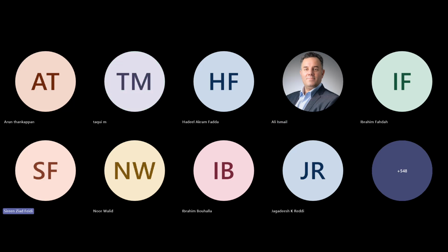They have to refer back to the circular. For specialized buildings, it is required to submit a BIM model. Although I doubt very seriously that the height of a hospital or a school will be above 20 or even 30 floors, the area might apply. If the area is above 30,000 square meters, then the structural model is required.